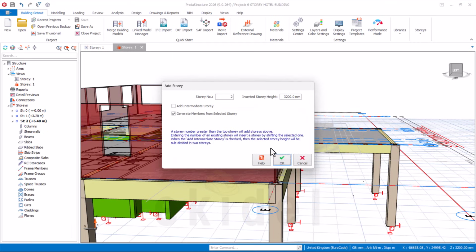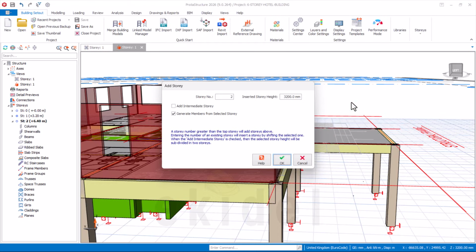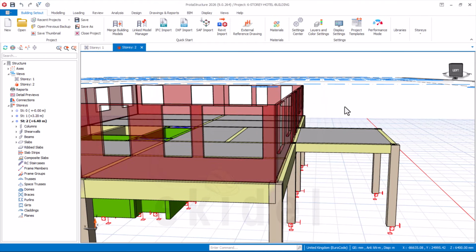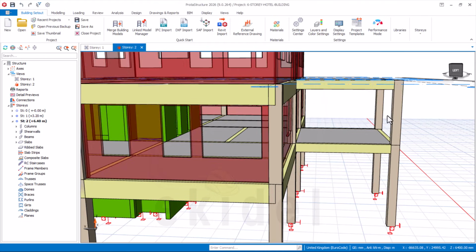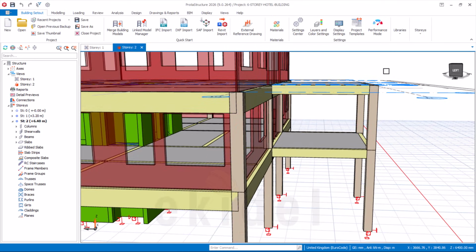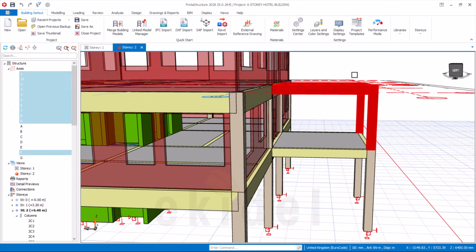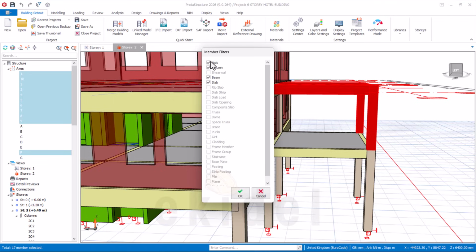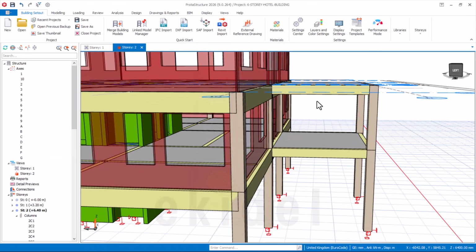That's fine. So now we will remove the other story that we have on this particular section here, this entrance porch. We don't need that on the other floors. It only affects the ground floor. So we'll highlight like this way, and then right click here and say delete. They will ask us a question. I'll say don't delete axis, but delete the rest. I'll then say okay here. So with that, we have those ones gone.